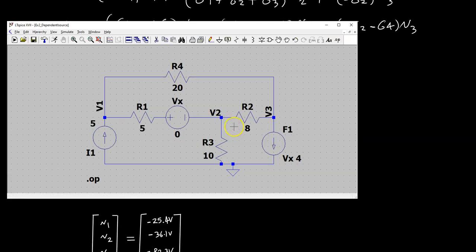Well, the issue with that is if I chose an independent current source and set the current value to 0, that means that I have an open circuit, so no current flows through that resistor. So the issue with the current source is that if I set a definitive value, I'm messing with my circuit now.